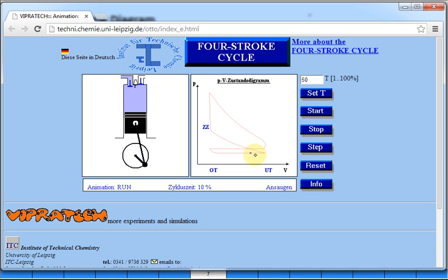Here the volume is increasing, and then it hits the bottom dead center. Now the volume's decreasing, the pressure's going up, so it's in the compression stroke. And then something happens, ZZ. Oop, look at that, it turns red, and the pressure skyrockets at constant volume. And now it's going down and expanding in the power stroke. The pressure's still high, and then you come down here and it rapidly drops. That's why you have mufflers. And there's a big blowdown. And then you're pushing it out.